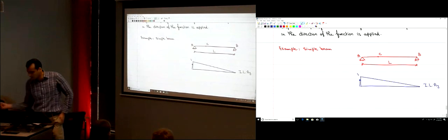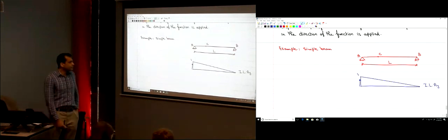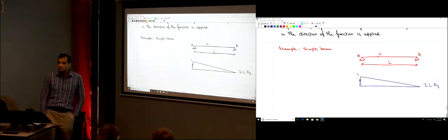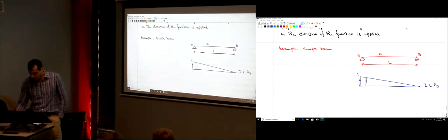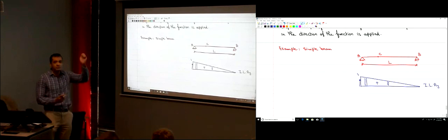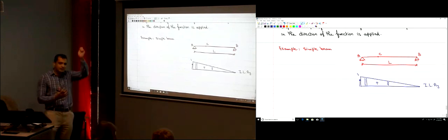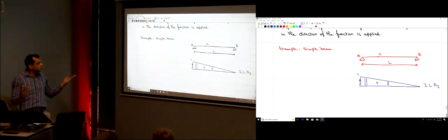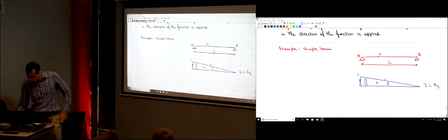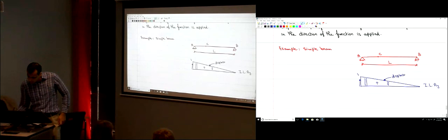Well, this is the displaced shape. This is how the influence line of A_y looks like. There is no calculations. It's all imagination that you move the beam, the virtual unit displacement in the direction of the function. This is the displaced shape over here that represents the influence line.